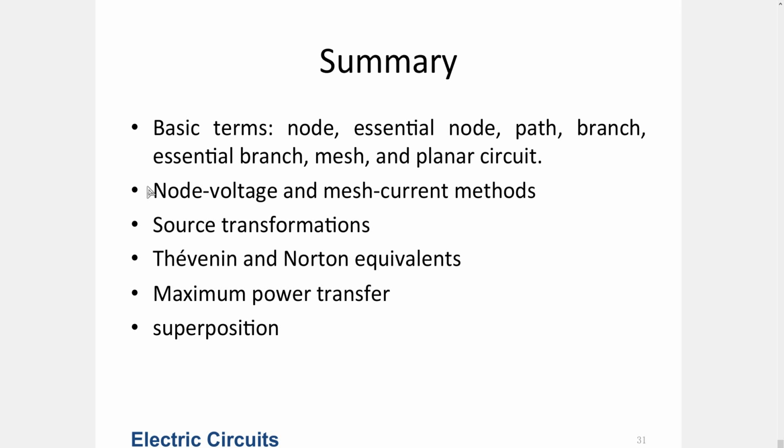We can apply it further to theoretical problems such as maximum power transfer, and find the conditions under which we can transfer the maximum power to an unknown load. What value should that load have in order to receive the maximum power? We know that for maximum power transfer, the load resistance should be equal to the equivalent Thevenin resistance of the source side circuit, whatever it is.